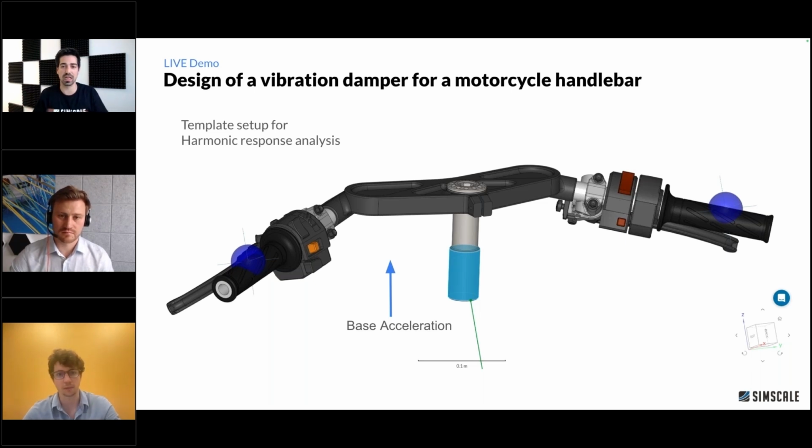Like we have a scale of 0 to 10, right? Very simple for the user to understand if they want to go for a rather quick turnaround time or for the highest accuracy. And I used the standard 5. But obviously, if you want, you can manually define mesh regions as much as you want. You can add refinements, boundary layers, sweep meshing, and so forth. You can do all that if you want to, and if you have the experience to know that this actually improves your results.